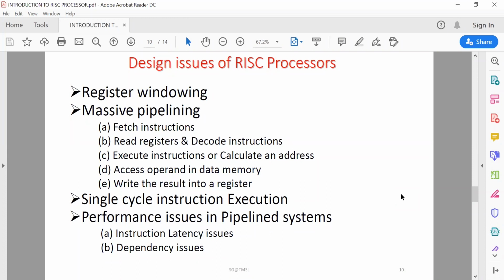instead of a push instruction to push parameters on a stack for the called routine to pop off, that processor just rotates the register window to give the called subroutine a fresh set of registers. The old window and the new window registers overlap, so that some registers are shared. And as long as you are careful about placing the parameters in the right registers, the windows are a slick way to pass operands without using the stack at all.